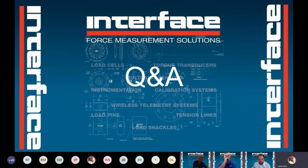Mike wants to know, does the BX8 provide the excitation to the sensors? Absolutely. And then we've got another question. For a 6-axis sensor, is the calibration done axis by axis or all axes simultaneously? Multiple axes simultaneously. So there'd be a force at an offset applied, which creates a combination of loads. So there's multiple combinations of loads applied during calibration.